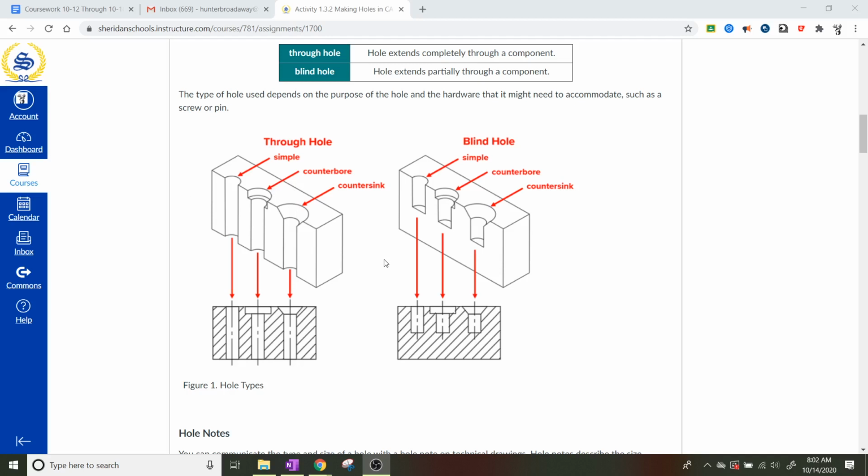A counterbore is a circular extra extrusion on the side, and it doesn't have any angle other than a 90-degree angle down at the bottom. If you look at a side profile of a counterbore, it goes down at a right angle like this. These aren't as common, especially in wood. Normally in wood, you're going to see the countersink instead, because most screws have this angle associated with it. A countersink is this extra piece of extrusion. It kind of looks like a chamfer whenever you're modeling it.